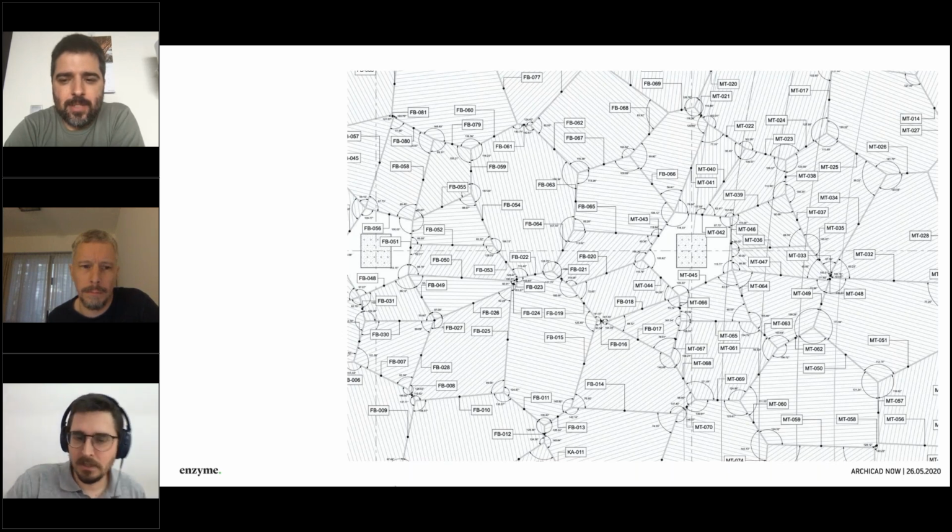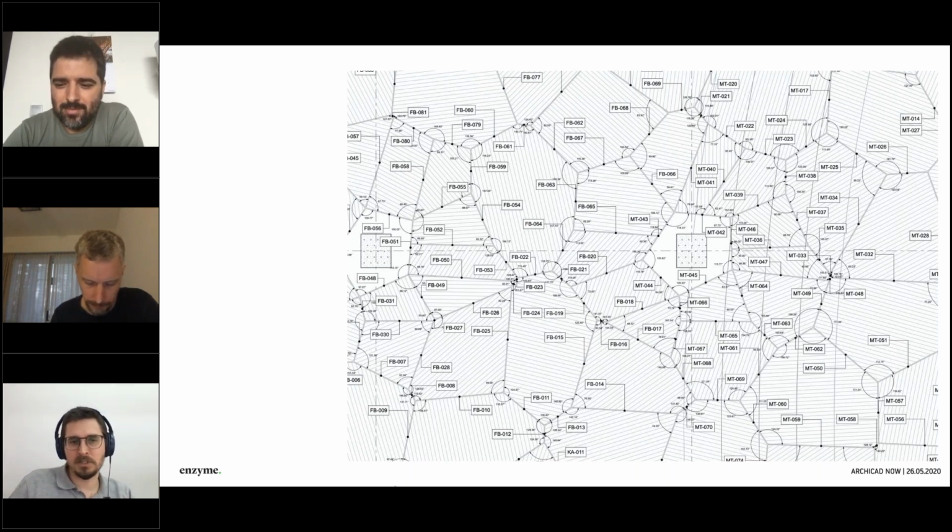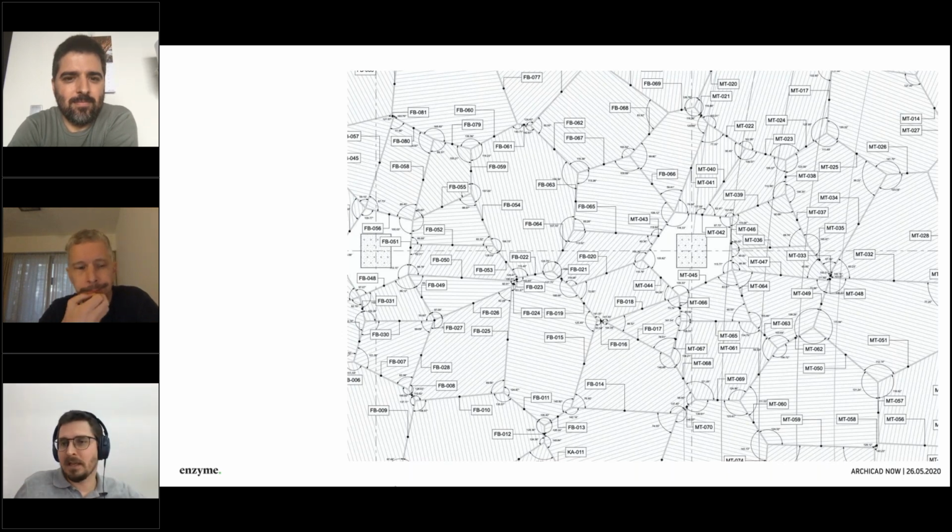Yeah, correct. But it depends on the fabrication method as well. For example, all the different panels will be fabricated through digital fabrication processes, because they're all different, so the naming has to be done parametrically as well. But the assembly of these components, because they're quite large, we imagine can only be assembled partially offsite. So there will still need to be some sort of on-site reference, and we will still need to check certain conditions on site. So we're still not there yet. I also don't know whether the digital capacity of the contractors our client is talking to is very large. So that's why.